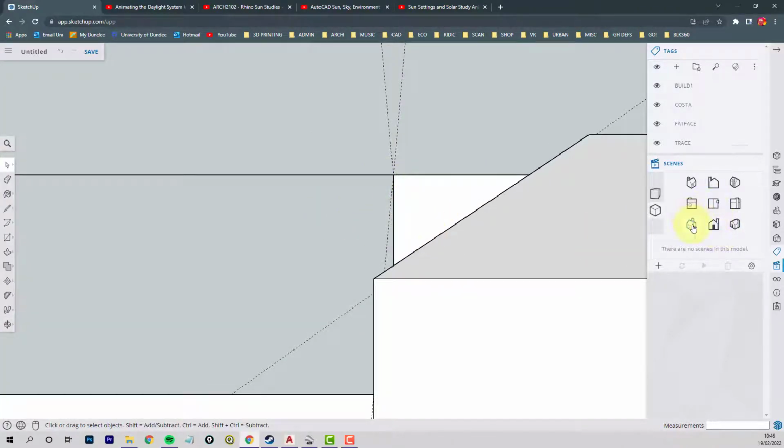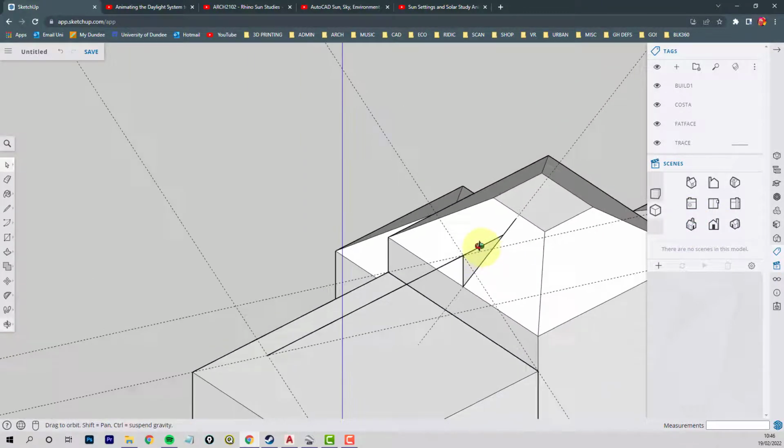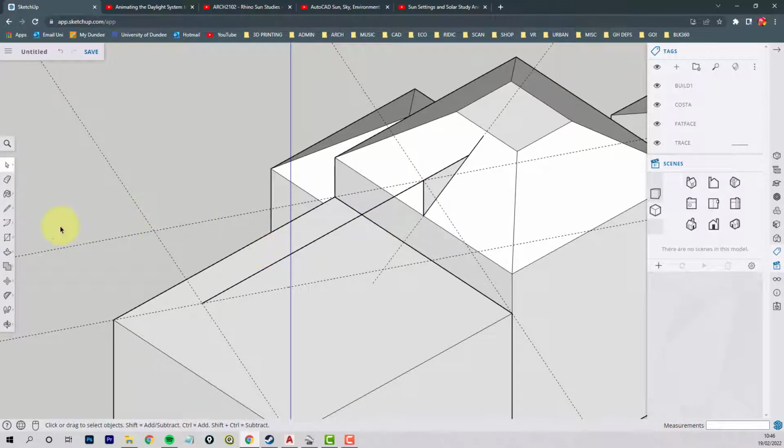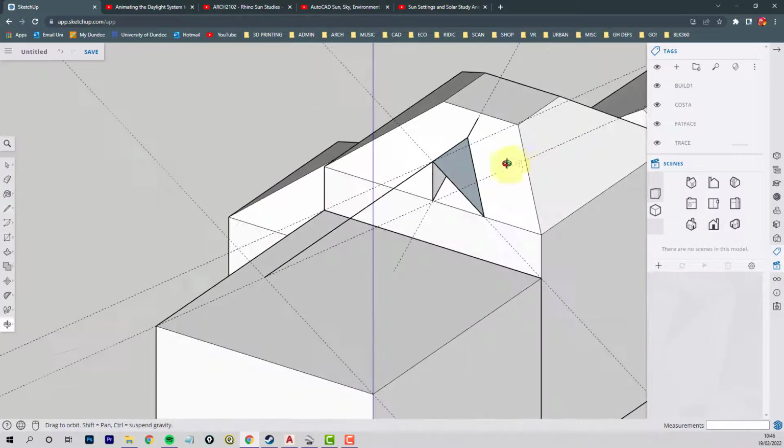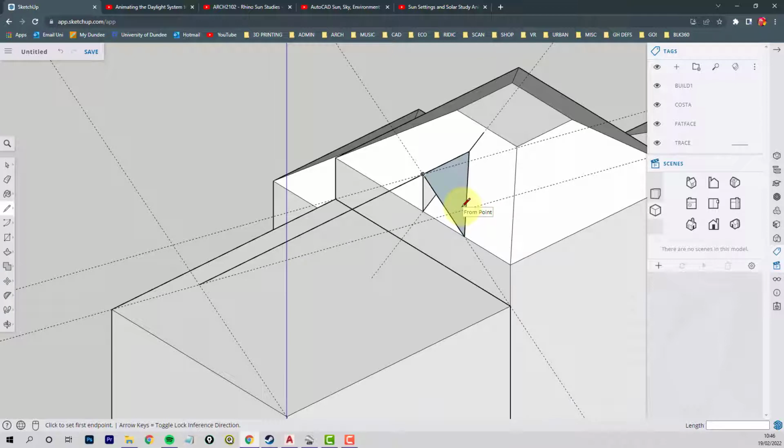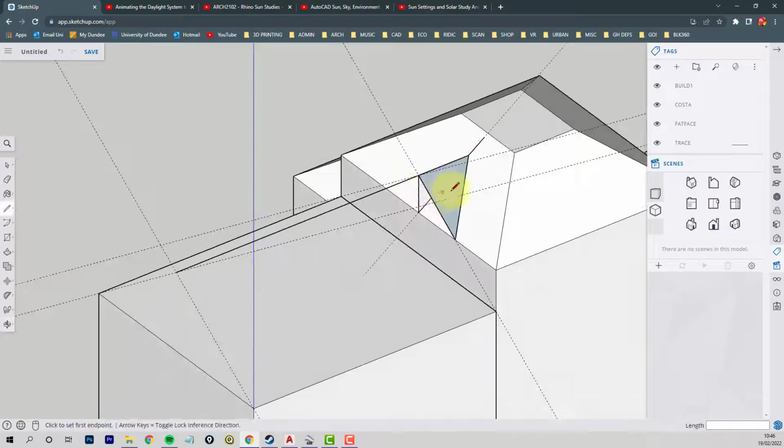So, you know, that's as good as I'm going to manage, I think. So we'll go back to that. That's given us positions we can now draw from, so we can fill in the rest of the roof shape. So we should have an intersection here. Okay, back up. That surface is facing the opposite way because I drew it clockwise. So I'll just demonstrate that if you've not seen this before. Maybe if I go this way I might get it to face the other way. No. So let's just take that line away. What I'm going to do is go anti-clockwise instead. So I'll take the line from there up to here. Okay, and then a line from here to here. Let's see if it's still wanting to face the wrong way.